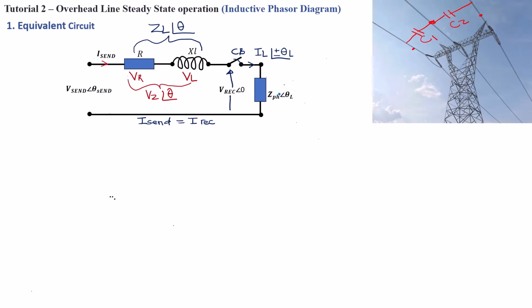Great. So to better understand the phasor diagram and draw it accurately for this short transmission line, you need to understand the characteristics of the load. This is why we did for a resistive load where the angle was 0 degree, right? The angle of the current was 0 degrees, so there was no phase angle, okay? But now in inductive load, the situation will change because the load is now purely inductive, okay? Now because the load is purely inductive, the current will then lag the voltage, right?